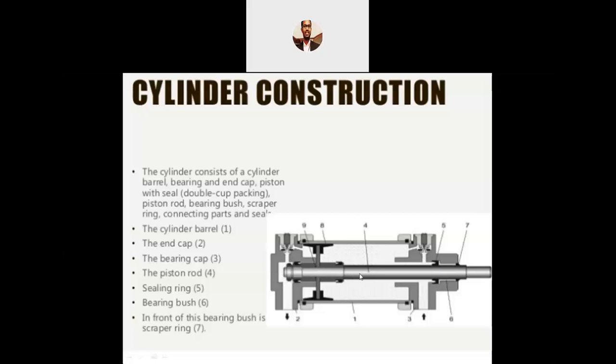moving parts. Now, my dear friends, this is the piston rod which will be moving inside and outside, extension and retraction. During this, a bush will always be placed over here. So due to this movement, whether it is a rotary motion or a linear motion, whatever vibrations or shocks are generated will be absorbed by these bushes. In most cases, a bush will be made of different materials, starting from copper to rubber. So based on the nature of the application and the principle, different bushes are used.